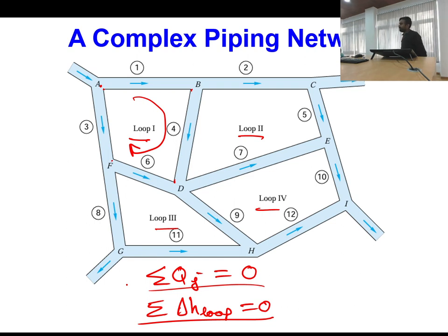Whatever ideas I communicated, is it clear? And remember one thing: once you solve an individual loop, if you have calculated some elevation at a junction, then you will consider this as a known parameter for all other loops, because at any junction, the head for every branch will be considered the same.